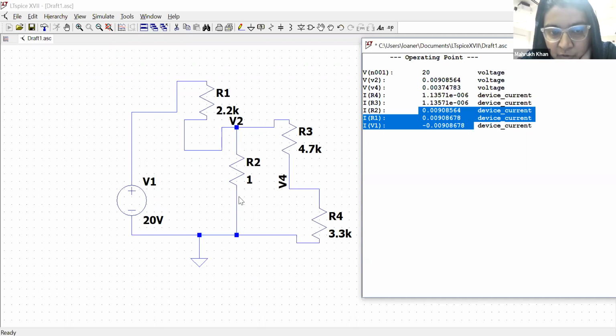So I just have 1 ohm. Shorting means that you don't have any resistance. It looks like the circuit that has only R1 in it, and this circuit will be cut off from the circuit we were having. What I meant by R2 short is that you are shorting this wire, so you will not have any current flowing here. You can also just replace it with a wire to see what will happen. Is it clear?